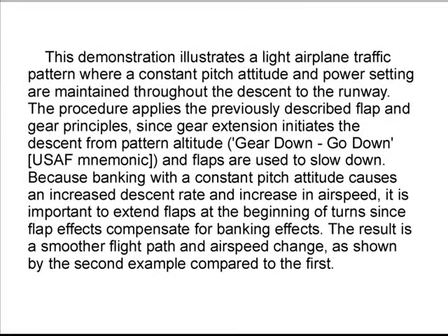In summary, this demonstration illustrates a light airplane traffic pattern where a constant pitch attitude and power setting are maintained throughout the descent to the runway. The procedure applies the previously described flap and gear principles, since gear extension initiates the descent from pattern altitude and flaps are used to slow down.